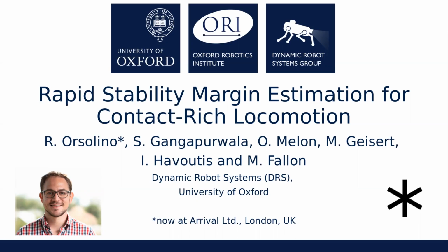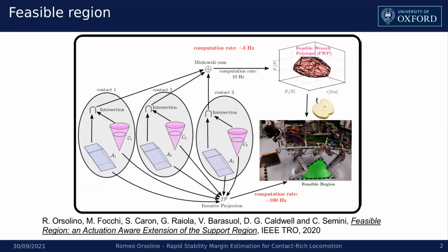This imposes the explicit consideration, at the motion planning level, of the main feasibility constraints of the platform, such as the joint torque limits. In our previous work, we had already developed an intuitive tool for the projection of the joint torque limits into a 2D plane, which can be used to plan the robot center of mass trajectory.